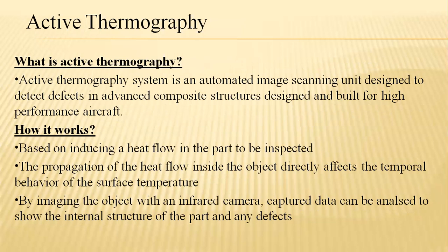So as we are discussing its capability, initially, what is meant by active thermography? Nominally, it's an inspection system, an automated inspection system utilized as a scanner. Particularly, we would like to call it an image scanning unit, specially designed for detecting defects in composite structures, which is designed and built for high performance aircraft.